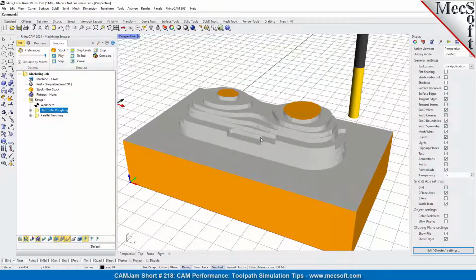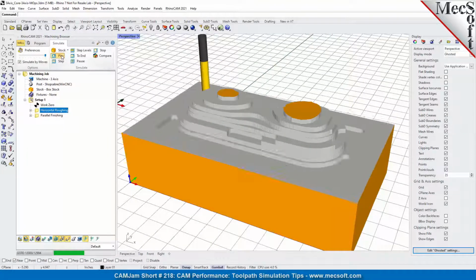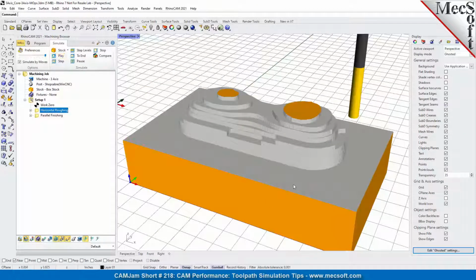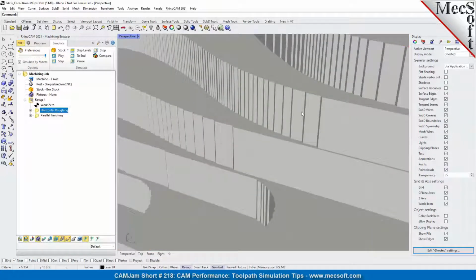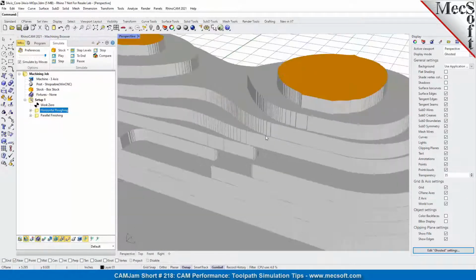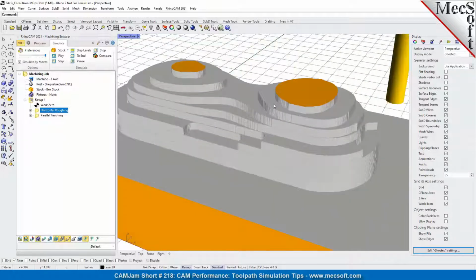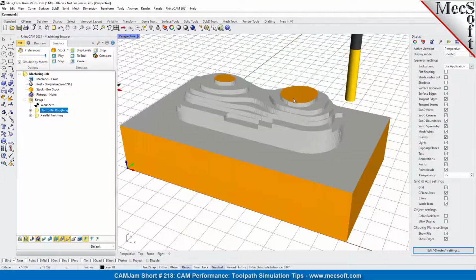So this is how fast it went through on the roughing operation. It took like 2-3 seconds. Now, Joe, you mentioned that there are some artifacts in the Z-axis. If you zoom in and you see these vertical artifacts, this is not in your toolpath. That is the voxels. You're basically looking at the voxels displayed there. So don't worry, it's not in your actual toolpath.